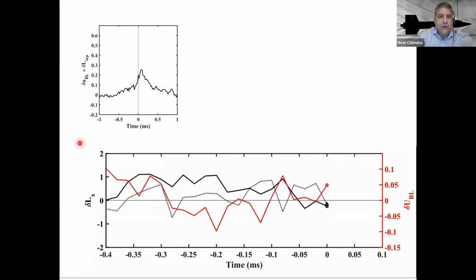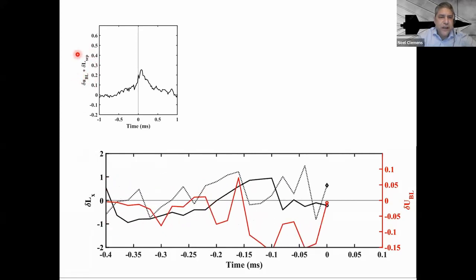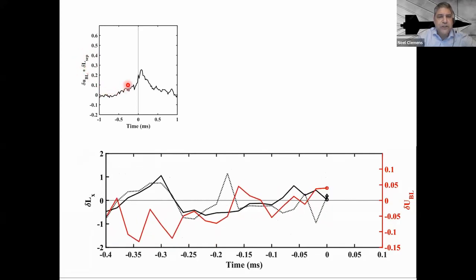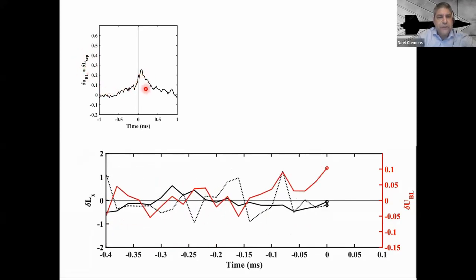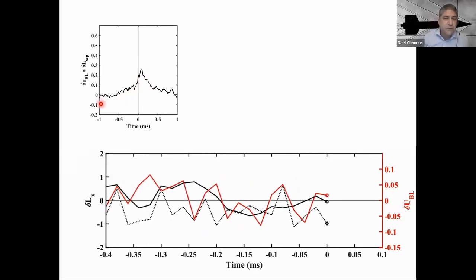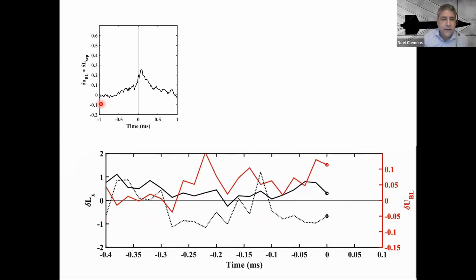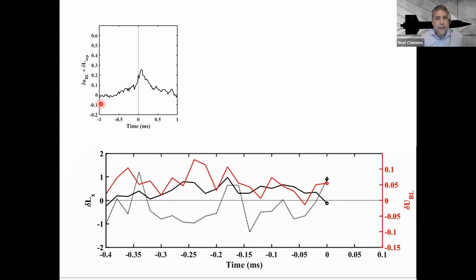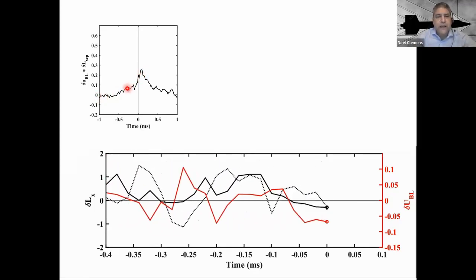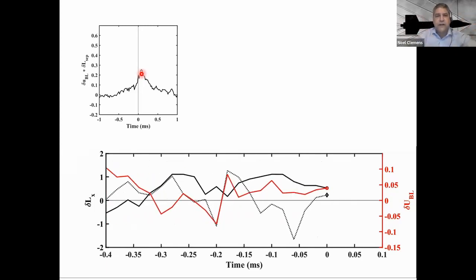And this shows their correlations. This is a correlation of the upstream boundary layer fluctuation and delta L sep, the separation line, and it's about a 30% correlation. This is pretty similar to a correlation that Priebe and Martin did in their study, where they were looking at mass flux fluctuations in the upstream boundary layer. They did not claim this was a dominant effect, though it was an effect.